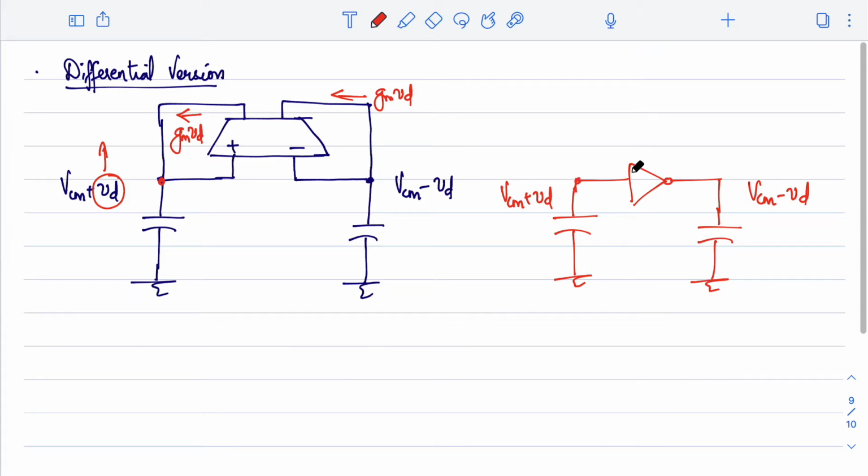What I need here is, if this VD is positive, this node should eventually regenerate and go to the VDD or the high voltage or 1. At the same time, if this voltage is smaller, this should actually go to 0. What should I do here? The simplest thing I can think about is an inverter, but just using one inverter in this will not help, because I should actually create a positive feedback mechanism.